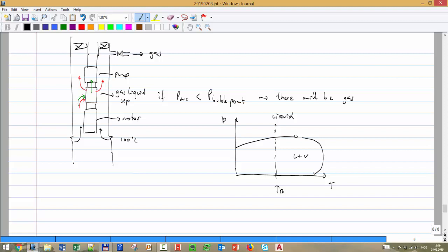And it has to do something with safety. We have here typically something that is a safety valve. If something happens, that's going to close all production from the well. But when we have flow through the annulus, actually we have a leak path. If something happens, the reservoir is completely connected to that annulus without any safety. So if you want to use that approach, you have to add a safety valve, which looks very strange.